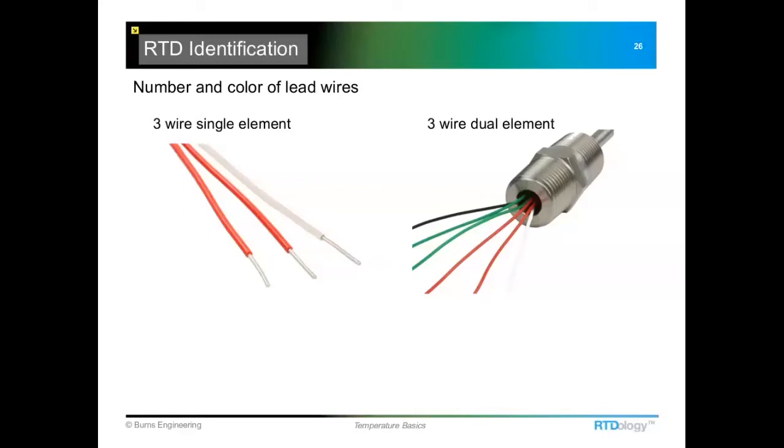So normally out in industry or out in the world, where you'll see thermistors is going to be measuring air temperature or fairly small differences in temperature. So anything typically related to an automobile, if you're getting a temperature reading on your thermometer in your car or your truck, that's usually a thermistor doing that. You'll have a lot of thermistors actually on the engine or measuring your cabin temperature, those types of things. They're very small, inexpensive, but much more limited range.